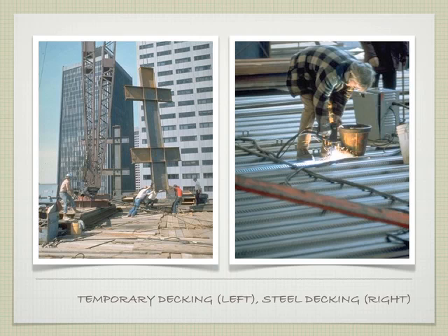Obviously, this guy is welding one of those shear studs into place. There's our row of the shear studs coming across. He's going to continue down this direction to tie that whole thing together. This is unrelated, but there's our two-story column. Joint at mid-height. Same thing at the top. Connections already welded together at the fabricator.